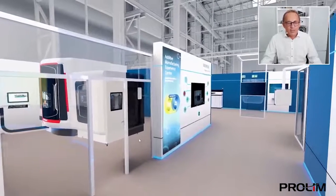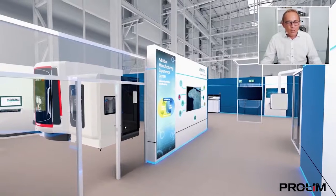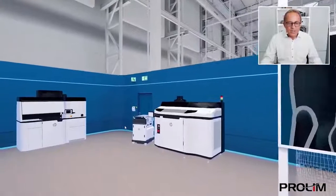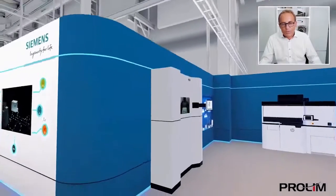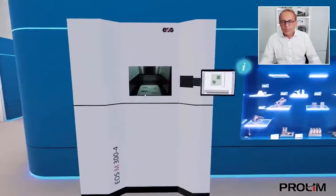Here on the left side, you see the DMG Mori LaserTec 65 3D machine, where we can do directed energy deposition, printing, turning and milling, all completely in one machine. If we go a little bit ahead on our shop floor, you see on the left side an HP machine representing the jetting technology, the newest HP industrial machine, the 5200. And we can also see an EOS machine, an EOS M300. This is a powder bed fusion machine where parts can be printed with a metal powder bed.